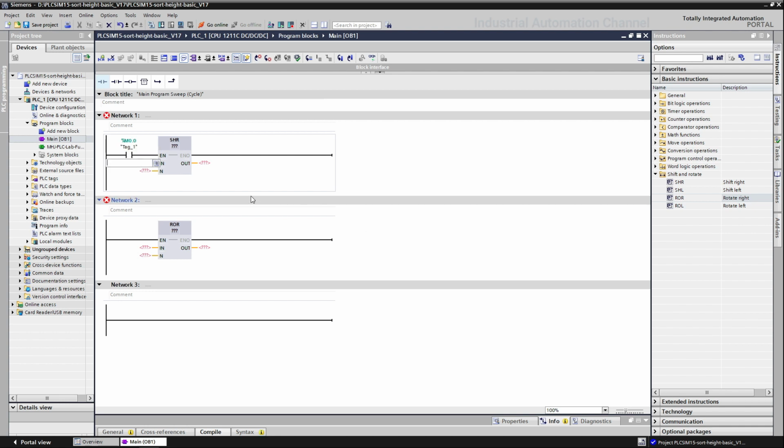But we cannot turn it on and off very fast in 5 milliseconds. It takes 1 or 2 seconds to do this, and during this time the shift or rotate register will be activated hundreds of times. So we define in the software for this button a rising or falling edge. In this case, with each activation of the button, the function will be activated just once.